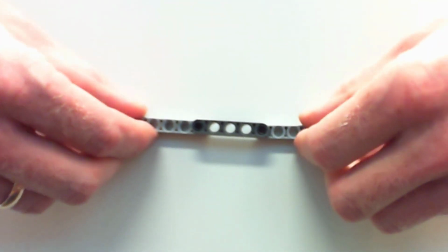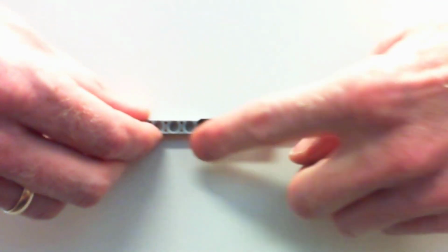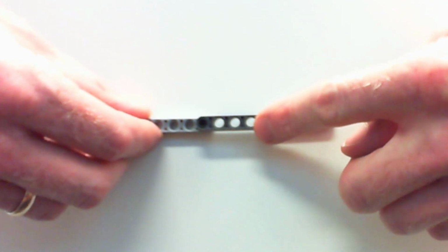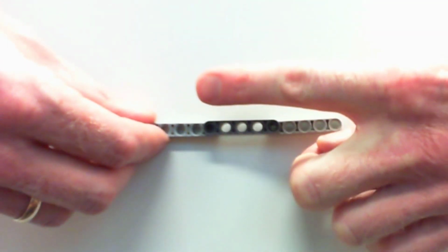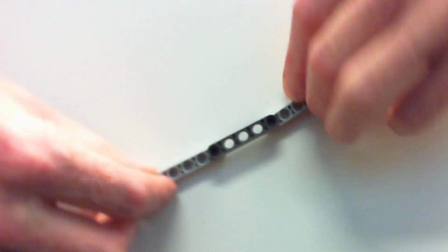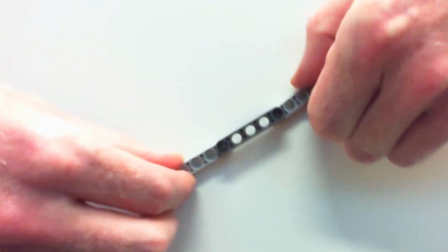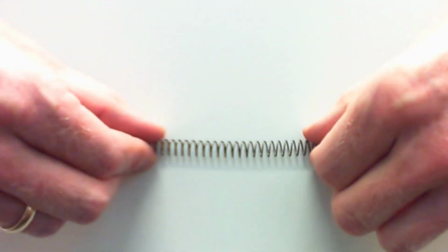But a weightless link is a two force member, and there's a single unknown, which is the magnitude of the force inside it. Its direction is always directly in line with that member. So if this member is vertical, the force is vertical. If it's horizontal at an angle, it is at an angle. The last two force member that we have possibly is a spring, and let's hold on to this one here.